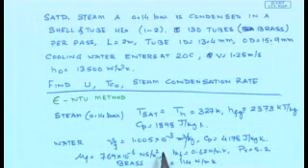If after calculation you see that there is a significant difference between the temperature that you have assumed and the temperature which you have obtained, so instead of 50, if you get 90, then the properties are going to be significantly affected, and you need to do one more iteration, just one more iteration, to ensure that you get the right values of the physical properties.